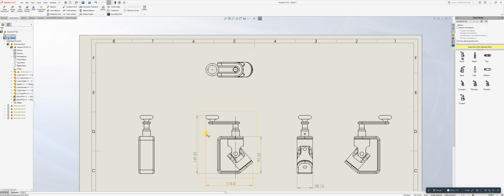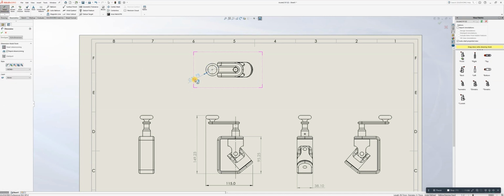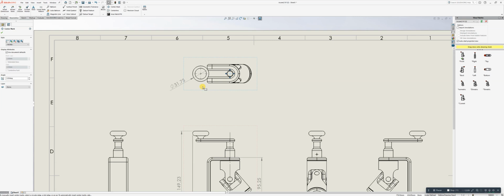Instead of me doing that there, I could do it to the centre of that there, because we will know what the diameter is. So if I just do smart dimension and do a diameter on that, this is a little bit too much. I can then go smart dimension from that centre point there, maybe to this centre point here. I didn't pick it up, did I? To that one there. Yeah, you can see that there. That's giving me an angle of 90 degrees. That's because it's freewheeling on that. I don't really want to do that.